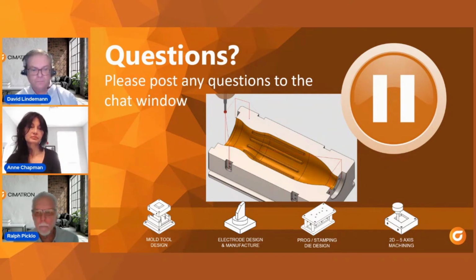So let's look at some of the questions here. Brad asks, do you need a seat for this feature or just the probe seat? This program that Dave has with the probing is an NC procedure. So we like to have it with the NC software. That way you can set it up to cut and check and then cut and check. And then you can make your adjustments on your tool paths.